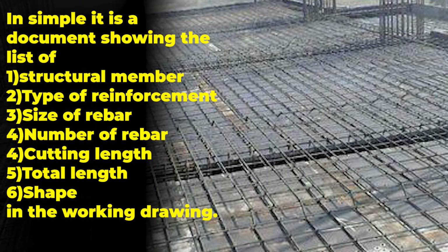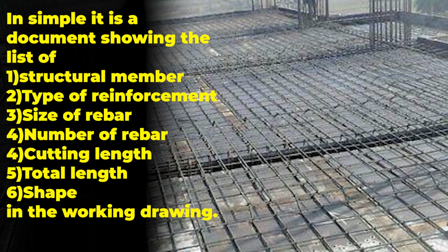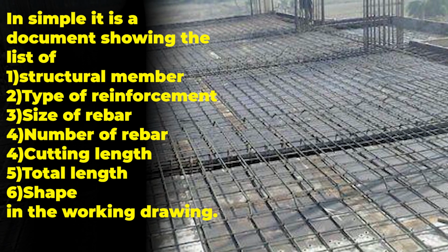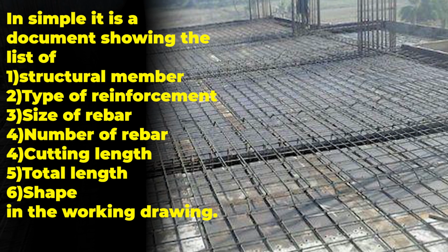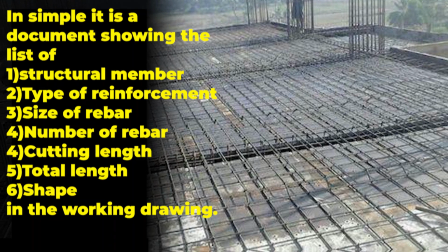So in simple terms, it is a document showing the list of structural members, the type of reinforcement, the size of rebars, the number of rebars, cutting length, total length and shape in the working drawing.